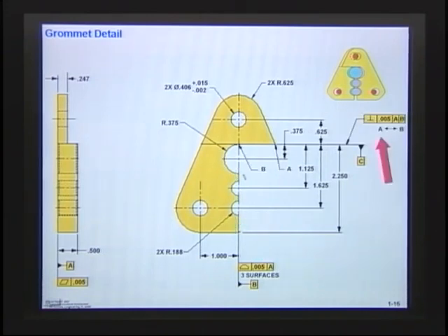Okay, let's take a look at what I did next. The next one that I did was this surface here. Now I could put a perpendicularity on that one because it's only an individual feature. Now, if you don't remember this profile, you have to take a look back in the fundamentals program, and I think you'll find this information in unit 12 in the fundamentals workbook. Here's what I did: I put a perpendicularity on here, and I said that this was to occur between A and B. There's point A and there's point B, because you remember these are 2 different surfaces.